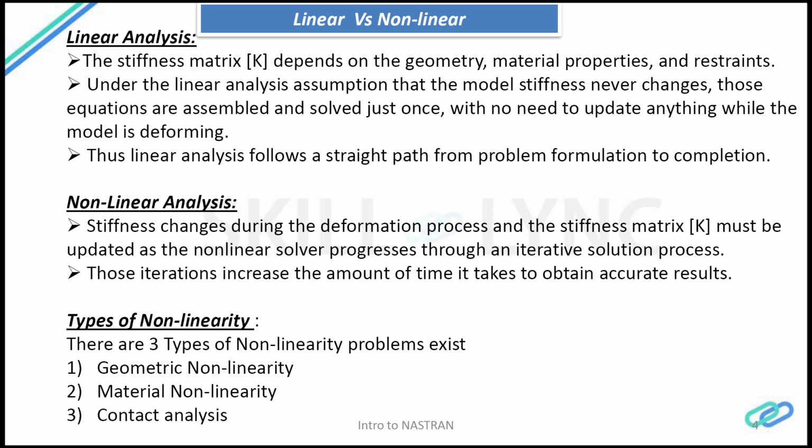In the linear static analysis, or the linear analysis, the stiffness matrix depends on the geometry, material properties, and restraints. Under the linear analysis, the assumption is that the model stiffness never changes, and those equations are assembled and solved just once.